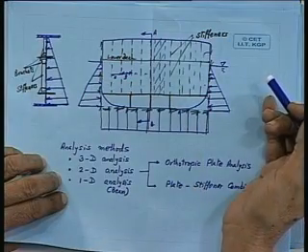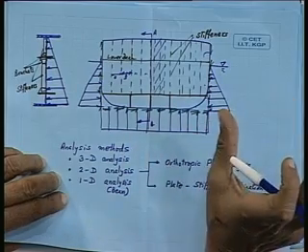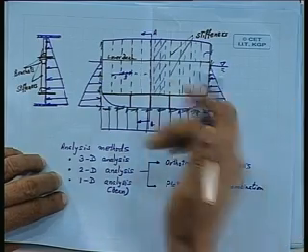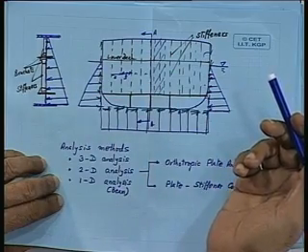The basic thing is that first of all, considering it to be flooded, there is no intermediate lower deck, therefore it is a single span with a triangular loading. Find out what is the maximum bending moment, where it is occurring, at which location, and what is the amount of that bending moment. Obviously, the other input will be the end conditions.